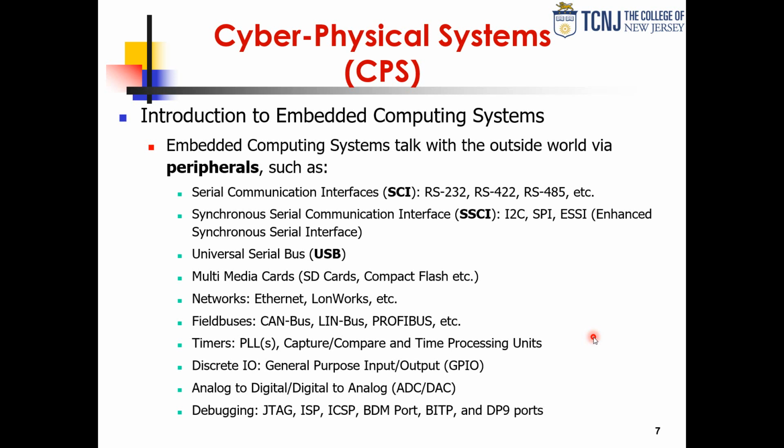Then another bus that is used as a field bus in cars is the LIN bus. So it's actually an evolution of the simple UART protocol. In fact, with software, you can implement the LIN protocol on a UART. Or it'd be better if you have the hardware. It's actually not that complex. But the LIN bus was conceived as a lower tier, lower cost, simple bus because they were using the CAN bus for the car for almost anything.